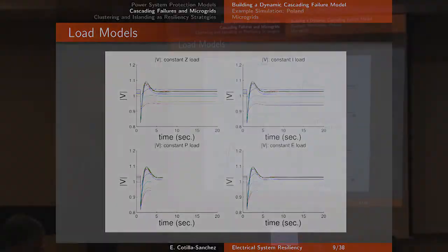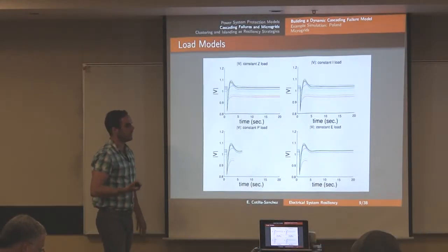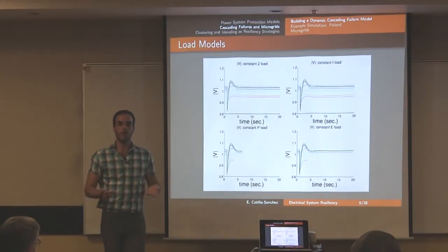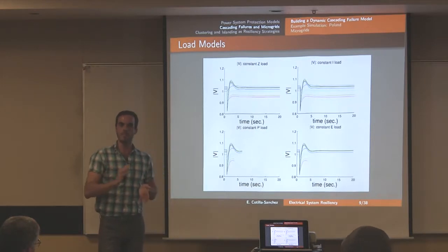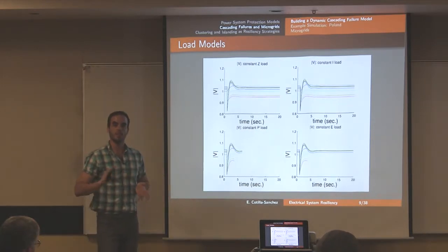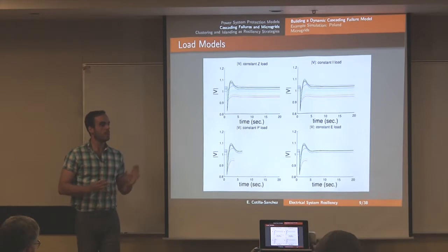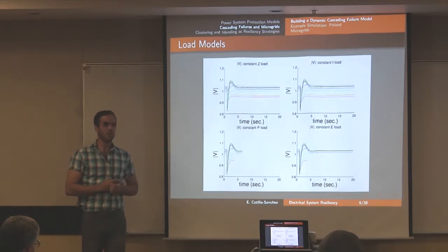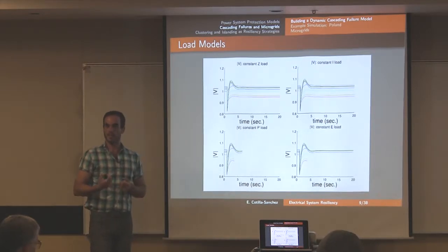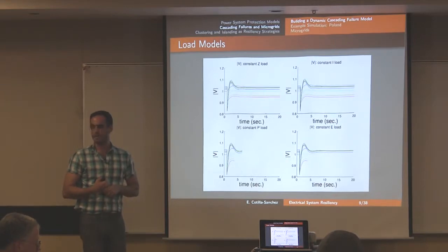Then things go a little bit crazy, and it's very likely that we will find cases that do not converge. Sometimes commercial simulators convert all of your loads to constant impedance so that they have a nice, smooth function and you can solve it near nominal operation. But that sometimes is not the case. We cannot model everything with a constant impedance.